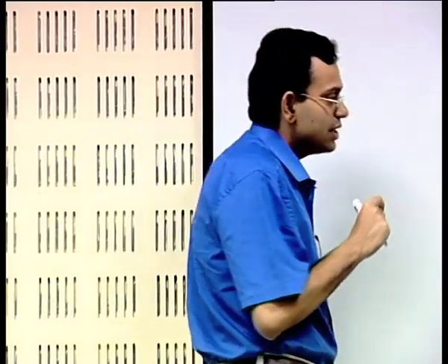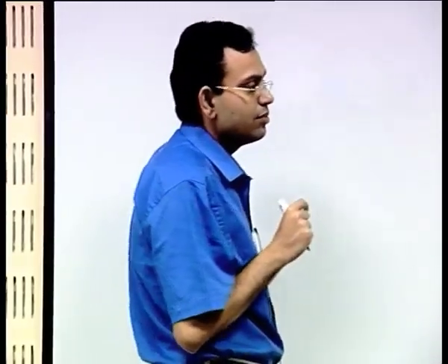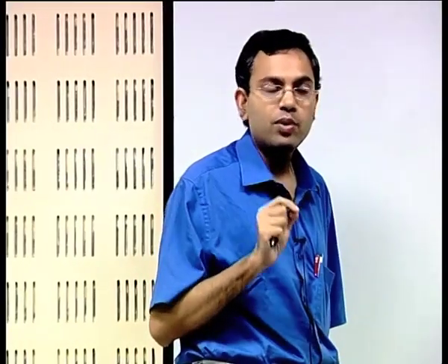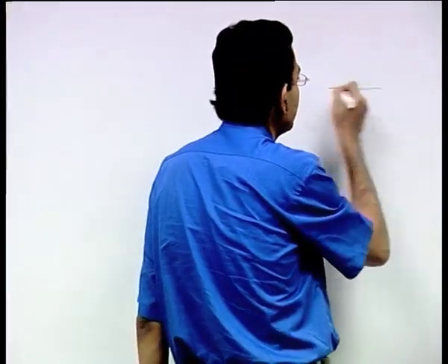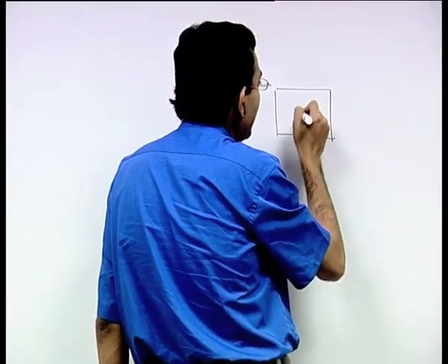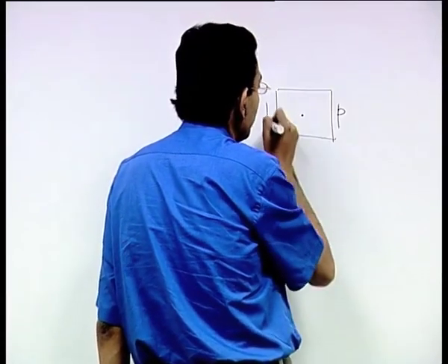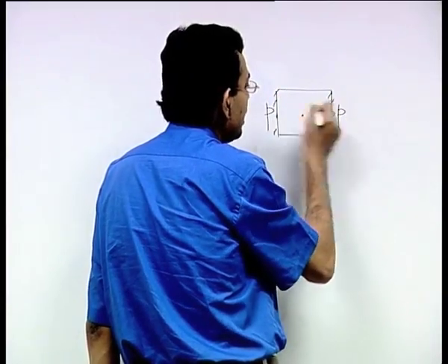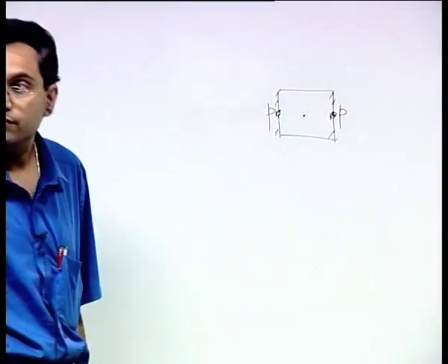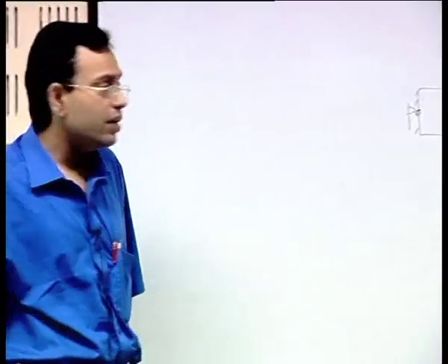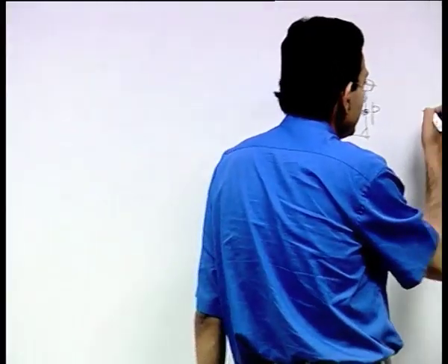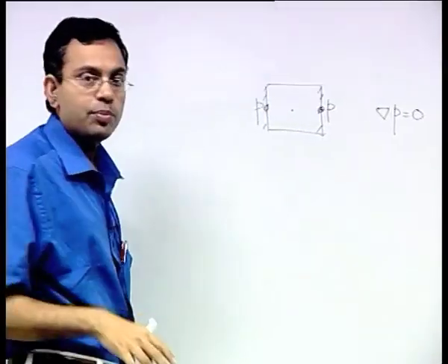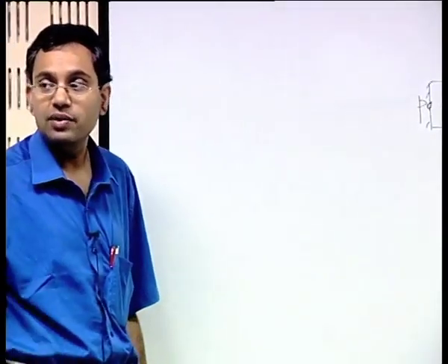See, the necessity of staggered grid was mainly there because of what? Because of interpolation of pressure at the faces of the main control volume, where pressure data is not directly available. So you have to interpolate. So if there are situations when the pressure gradient is 0, then the requirement of pressure interpolation is nullified, pressure no more acts as a variable.